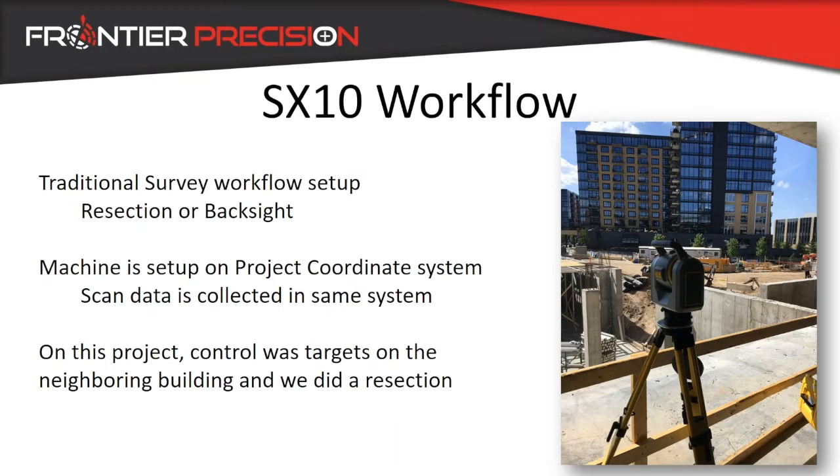So I did a resection to set up my machine, got my residuals, was happy with the results, and from there I was ready to go.